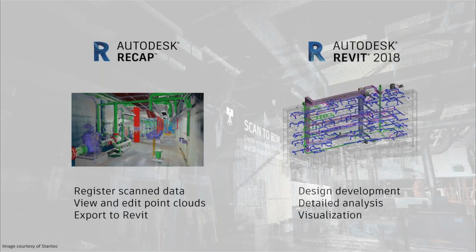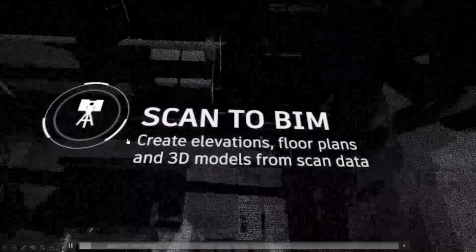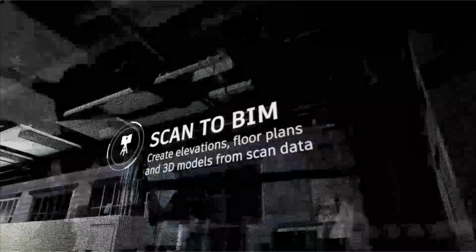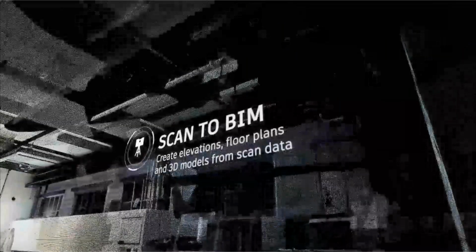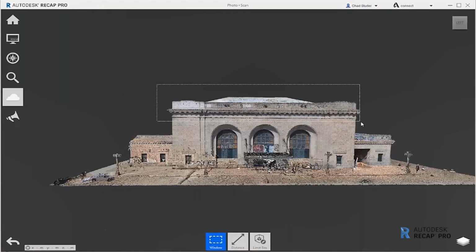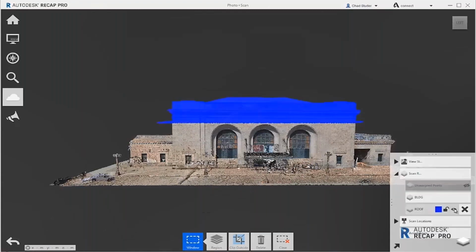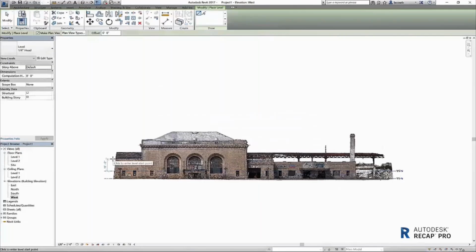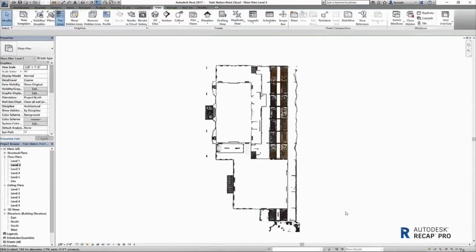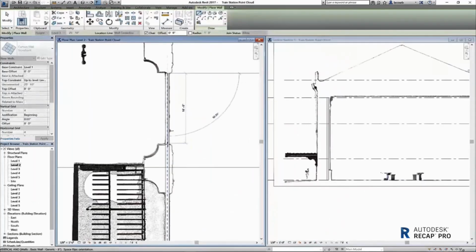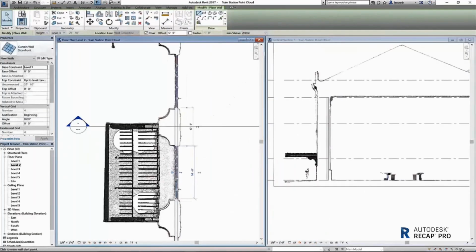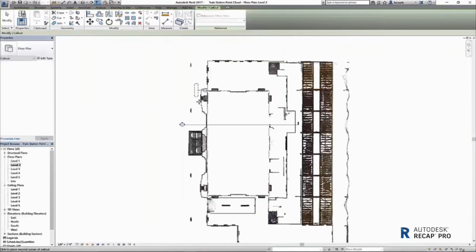So when you're doing the scan to BIM process, for example, let's say I'm placing laser scan data on a multiple site location, different coordinates. I'm scanning this complete building. So this building has been brought into Revit, and you can see it's not actually a 3D model, it's just points, okay? But it looks like a complete 3D model. It's just millions of points you can see. If you zoom in, you can see the complete points over there, okay?